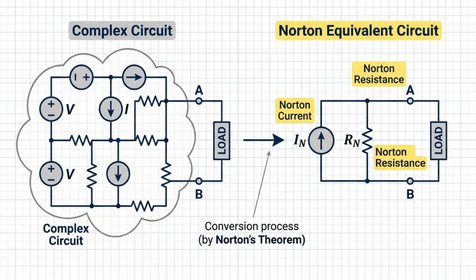At its core, Norton Theorem is not changing the physics of the circuit, it is changing the way we represent it. The external behavior stays the same, while the internal complexity is replaced by a mathematically equivalent model that is easier to analyze and reuse across different load conditions.